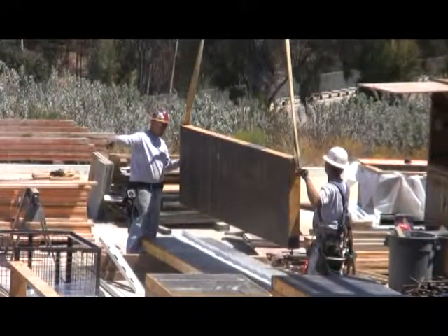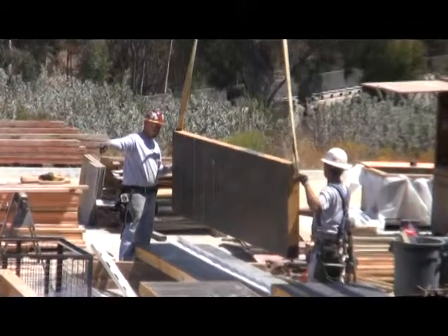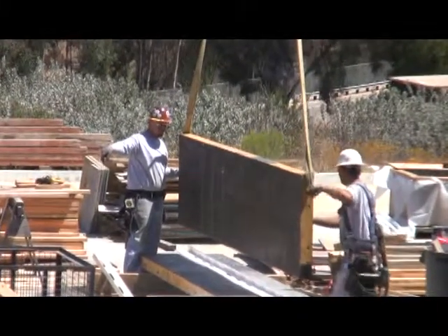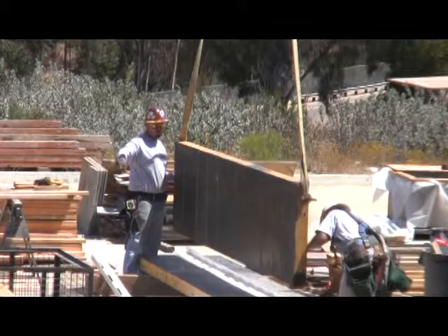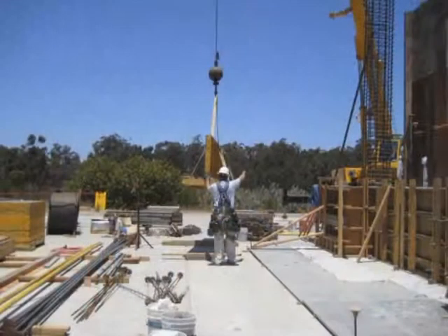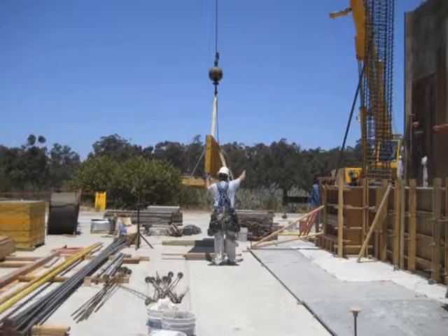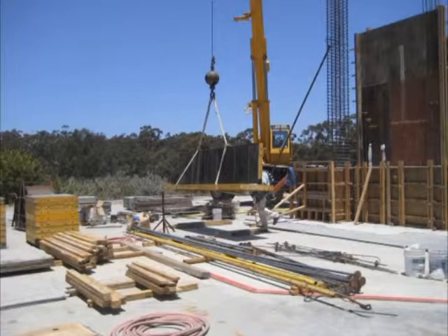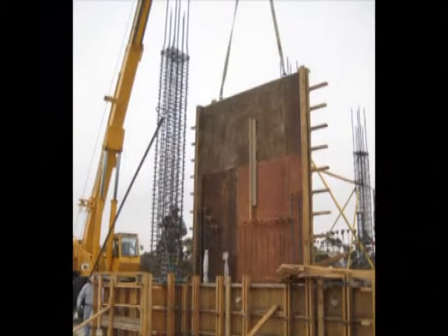After installation of column rebar cages and completion of pouring the foundation concrete, formwork for the shear walls and columns are installed simultaneously. Formwork is the general terminology used to describe the temporary mold into which the material is poured, in this case concrete. In the construction of the columns and shear walls, the formwork is often erected on-site from prefabricated segments which are constructed off-site. In this example case study building, the formwork for the shear walls was installed first.